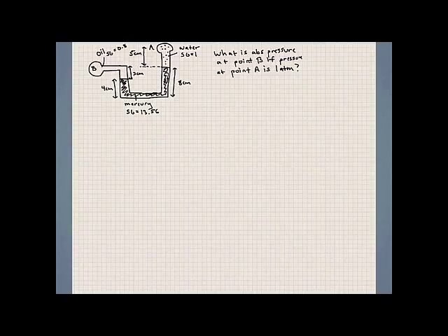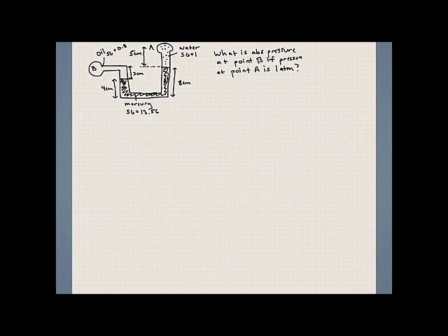Now let's remember what specific gravity is. I'll write it here so that we can see. Specific gravity is the ratio between the density of the fluid that we're interested in to the density of water at 4 degrees Celsius, which for our class, we'll always assume it to be 1,000. So, if we multiply the specific gravity value that we're given for any fluid by 1,000, we will get the density for that particular fluid that we're interested in.